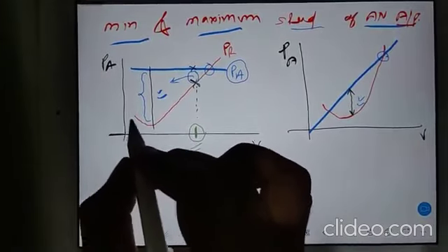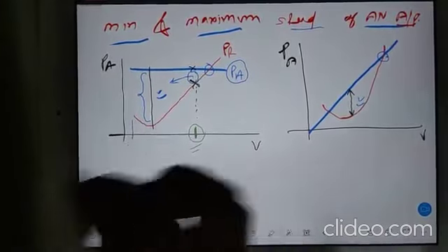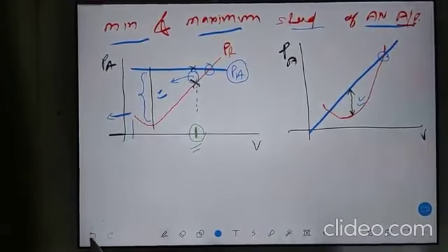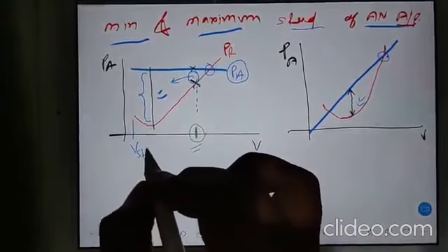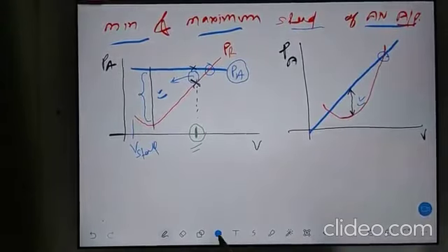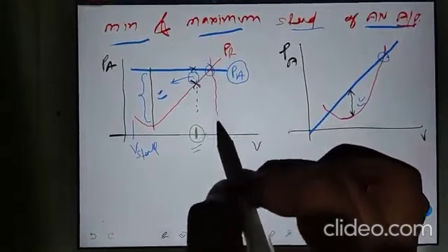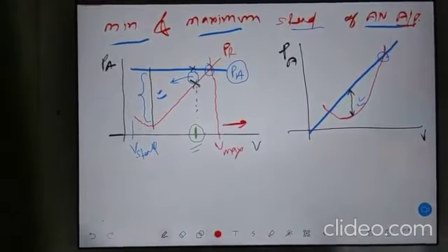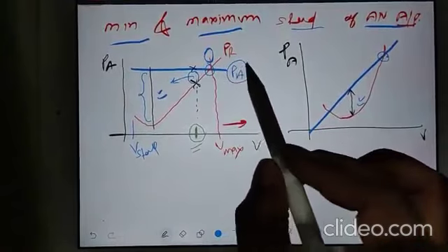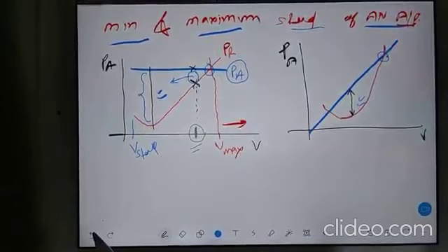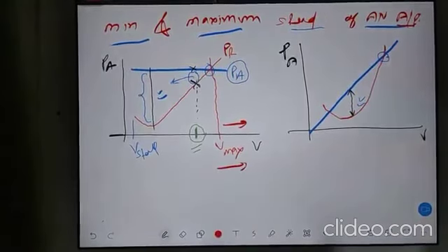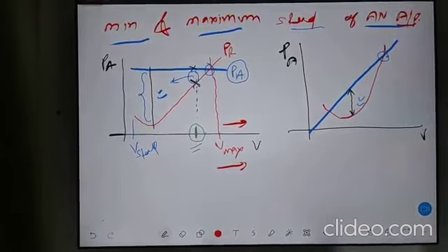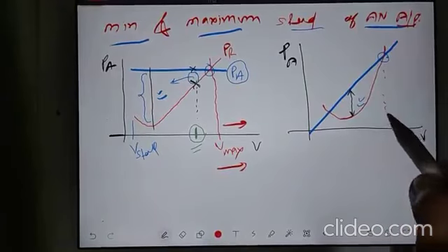And one more thing you check. The last velocity is here. Before this, if you go, you don't have a graph, so it means you will stall. So this is your stall velocity. And this is the maximum velocity you can produce. After that, you cannot produce velocity. Why? Because your power requirement will be more than power available. So it means you don't have sufficient power, so your airplane cannot fly. So this is the maximum velocity. In the same way, this is the maximum velocity here.